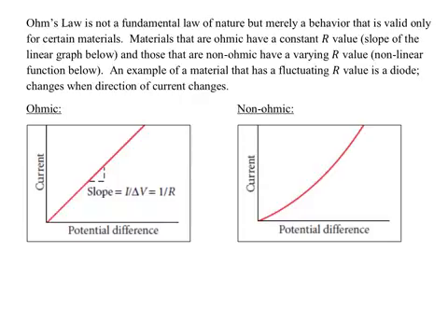These graphs are just showing you, if you look at this carefully, you've got current and voltage. If you look at the ratio of current to voltage, current over voltage is 1 over R, because in the previous slide we wrote down that resistance is voltage over current. These graphs are from your text. If I'm looking at current to voltage here, I can see that the whole way, this has a constant slope. Well, R is really like the slope. In this case, it's 1 over R.